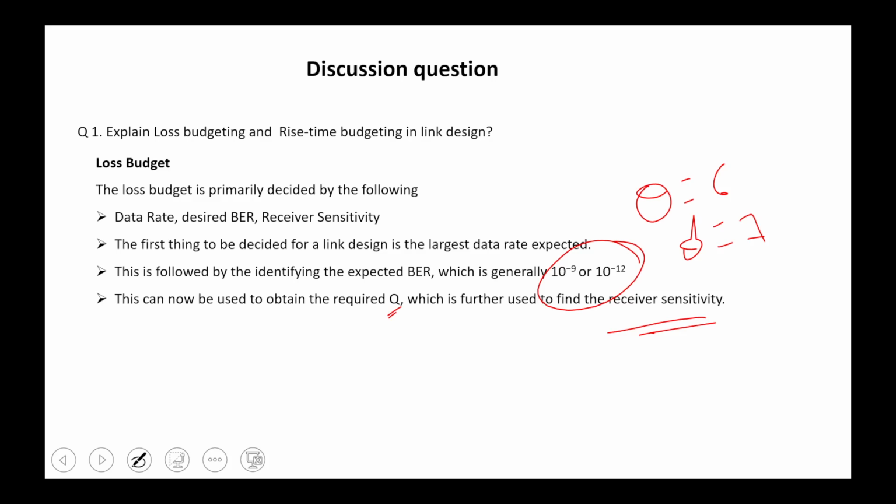Okay. So the next thing to decide related to the fiber length is attenuation. Another parameter for link design: how much fiber length we use, and how much attenuation loss that fiber has, which we have to calculate in dB per kilometer. We also have to calculate the number of splices and splice loss, meaning the losses due to the connector splices between the fiber and the amplifier, and the connector between that amplifier and the transmitter. We have to consider those losses in the design of the link.